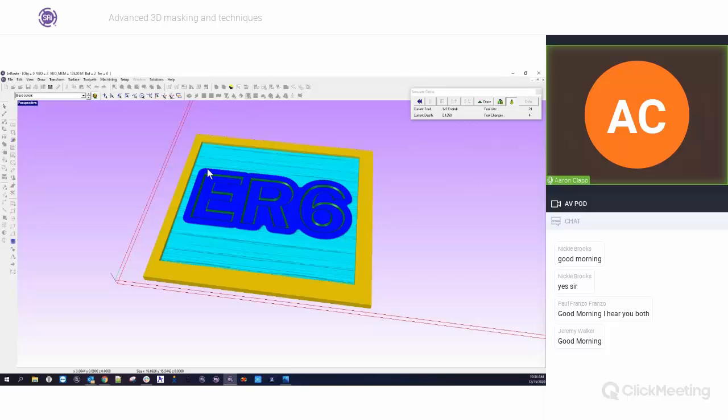The more 3D effects that you stack on top of an object, the more complex it gets, and the harder it becomes to manage and toolpath. Doing it this way with masks is also a big time saver. The more that you can do with two-dimensional toolpathing, the better you're going to be, simply because of the overlap amount.